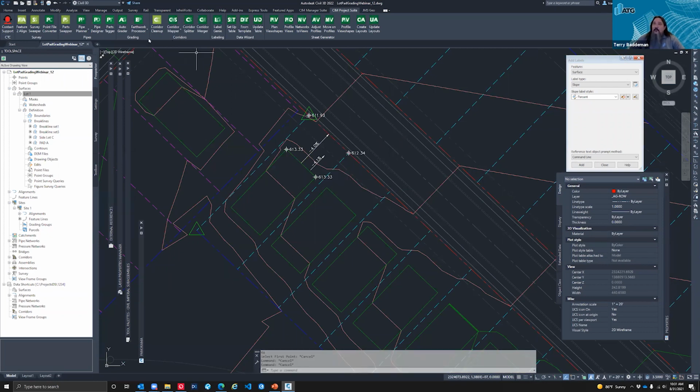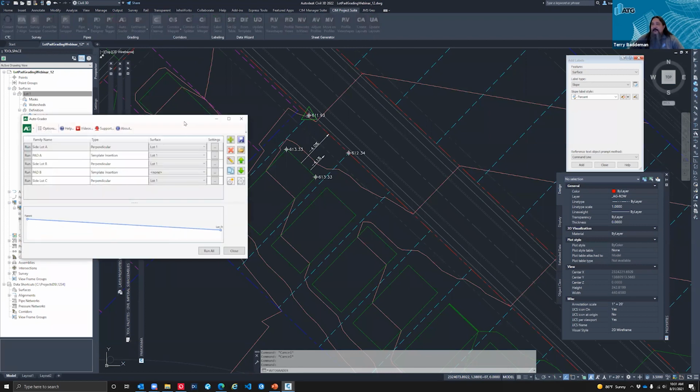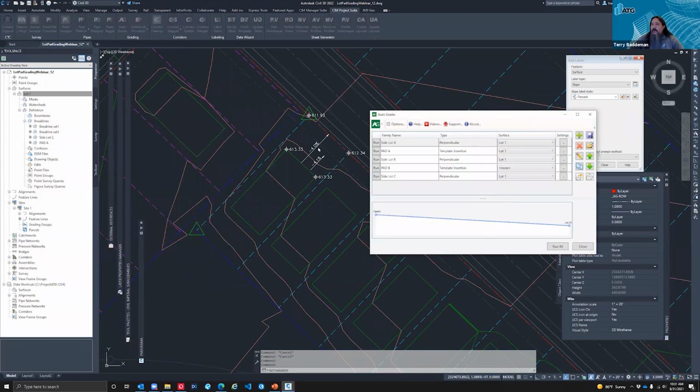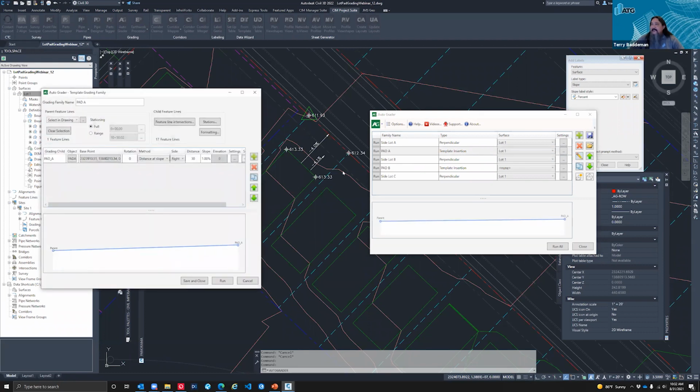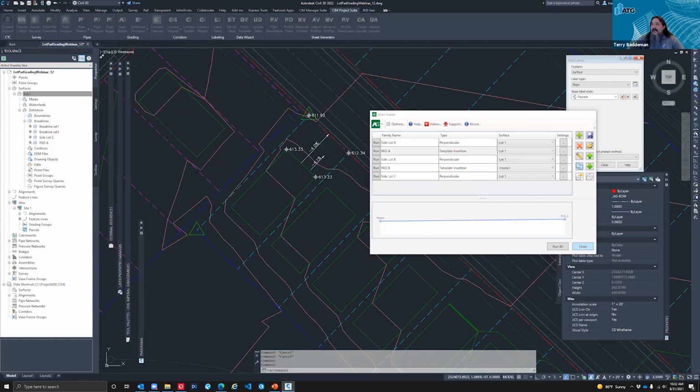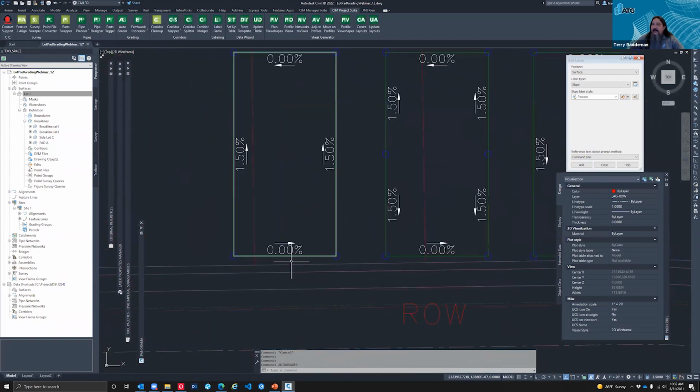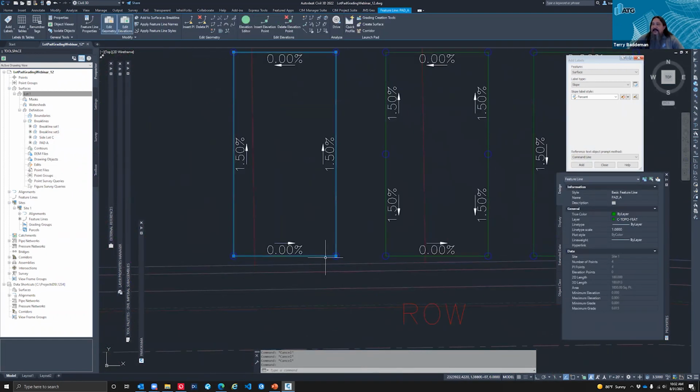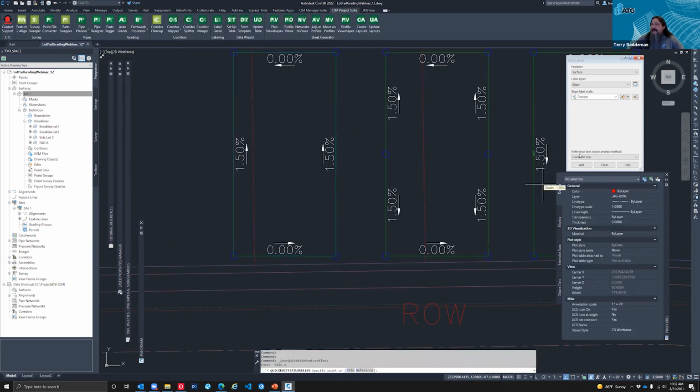Okay, so our pad is actually relative to the elevations, and even though we're designating this as a 1% slope, it's calculating out as a 4% slope. The reason is that when we look at our actual pad, this elevation at the front of the lot is at a different elevation.